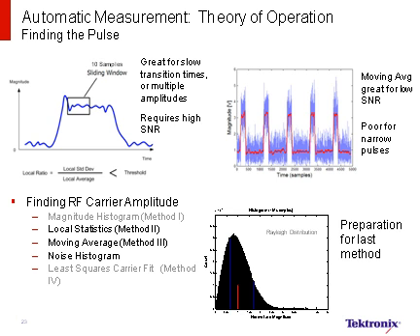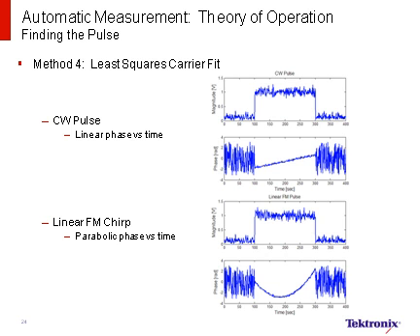The last method of detection is called the least squares method. It was devised to improve the ability to find pulses which are narrower and have a lower signal-to-noise ratio. For speed and increasing the probability of detection, if the user can enter the basic modulation type, whether it is a CW or linear frequency modulated chirp, then the algorithm can use this knowledge to greatly increase the probability of detecting the pulses that are in the noise.